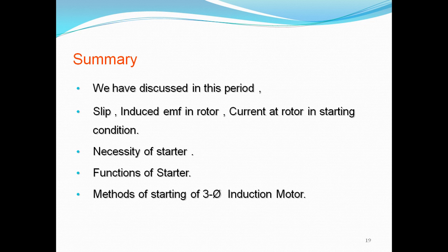Likewise, we can use starters for starting the motor, and not only starting the motor, it will protect the motor from overload, and if the supply is suddenly gone, in this condition also it will protect the motor. So that is the purpose of starter.